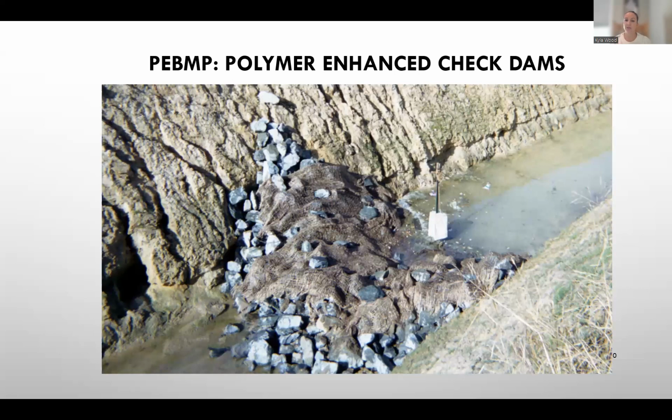They can dry out between rain events, so it can take 15 minutes or so to rehydrate once the water starts flowing. So if we use a combination of the solid log form and the granular PAM in these types of applications, we get our fast acting polymer, and then we also get our long lasting polymer.